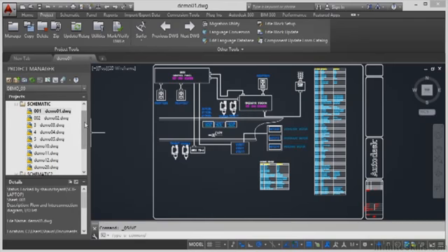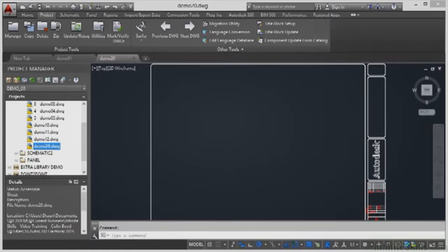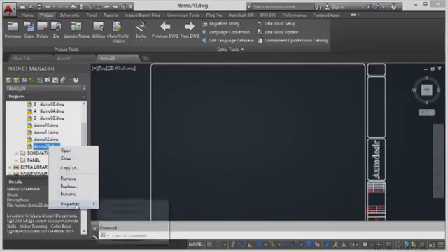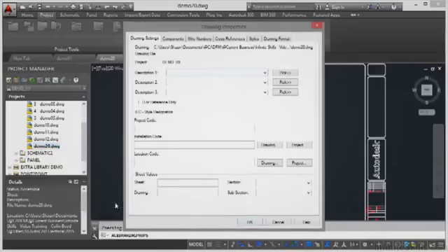Now let's scroll down to that new drawing that we created, Demo 20. If I open that one up, you'll see that there's no description, there's no sheet number. So how do I edit those details? What I do is I right click on the drawing in the drawing list, go to properties, drawing properties here, and I can now put the description and the sheet number in. Sheet number 020 because it's number 20, and the description I'm going to put in is AutoCAD Electrical, that's the abbreviation for it, and I'm just going to put blank drawing, like so.